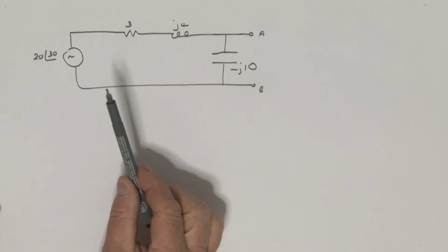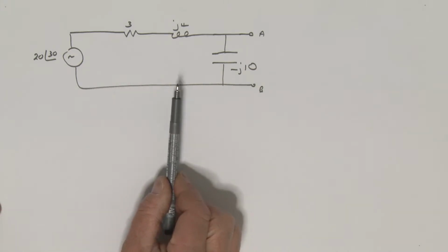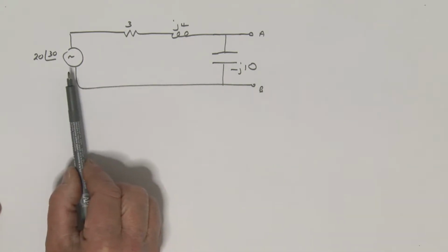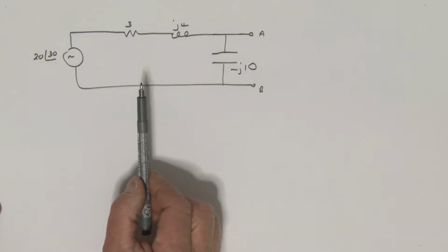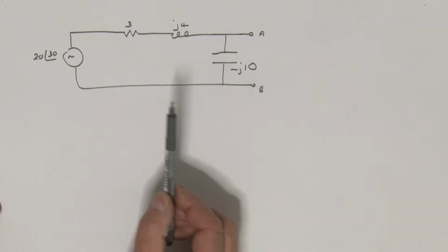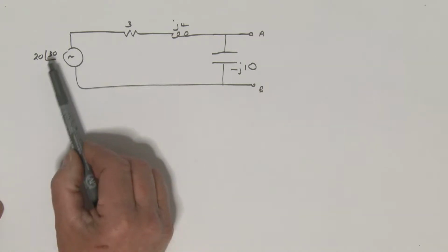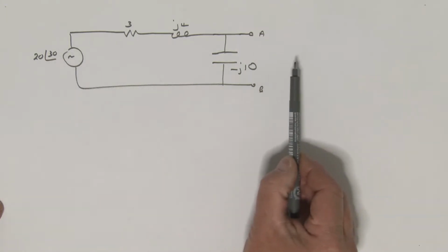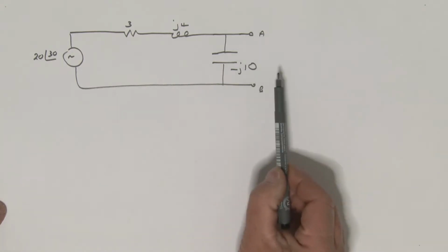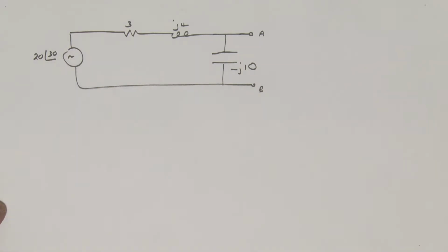Okay, look, we've considered this circuit in terms of finding the Thevenin impedance. We've looked at two different approaches. Note again, we've got an independent source here. So we said that we could find the short circuit current and divide that into the Thevenin voltage, or we could zero all our independent sources and look at the impedance looking in at those terminals A, B, having zeroed everything inside.